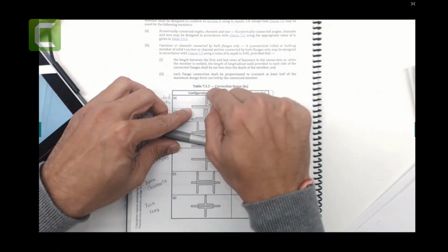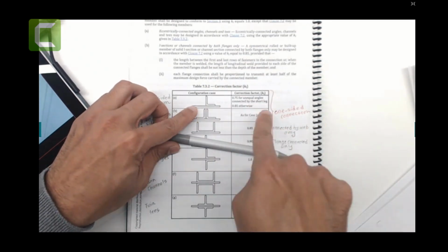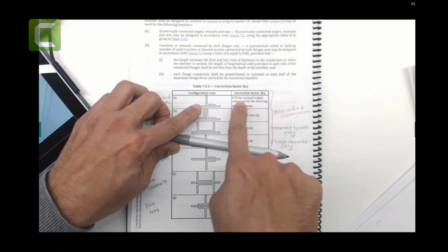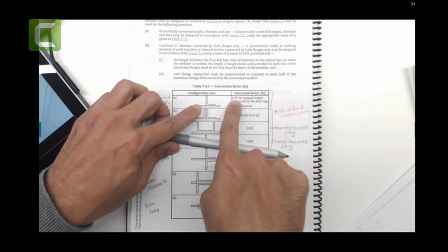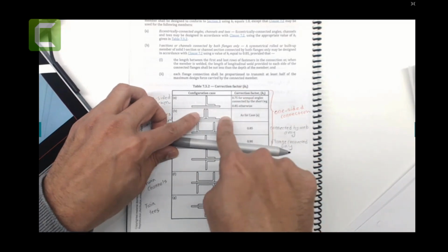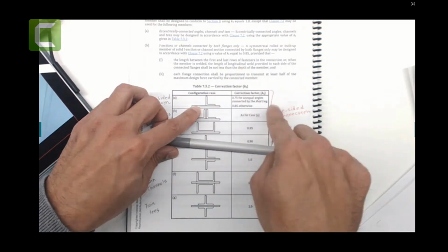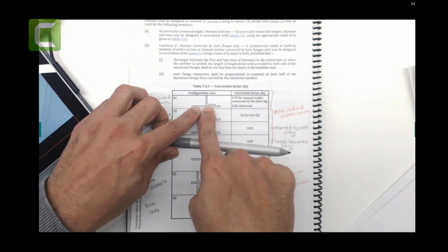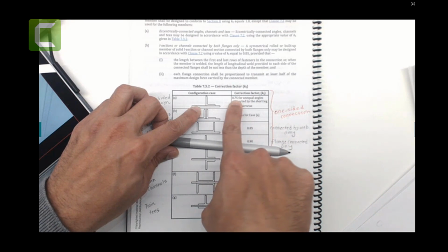In this one, you have everything. So you have another plate here as well, by the way, that is not shown here, but we have an unequal angle, connected by the short leg. Yep, short legs. You can take it as 0.75, and that is the one-sided connection. Standards don't like it, meaning that you have non-uniform stresses generated due to these one-sided connections. Therefore, you have eccentricity. So therefore, we take KT equal to 0.75.